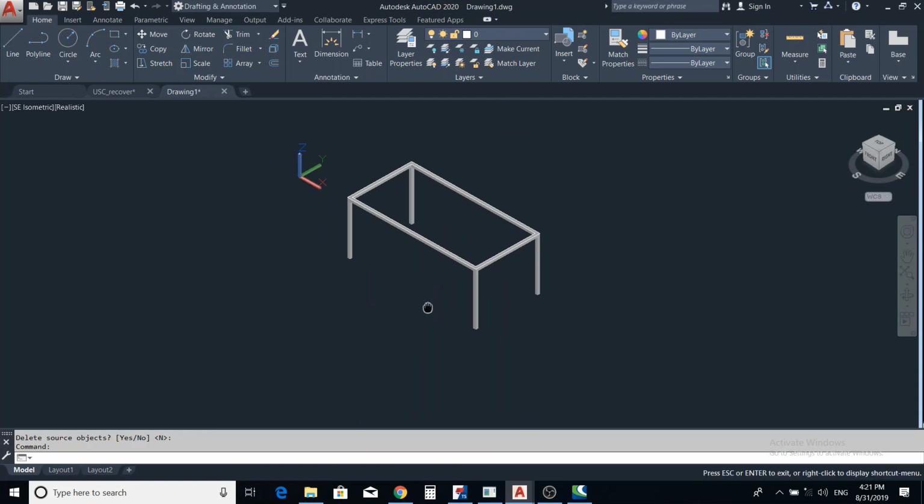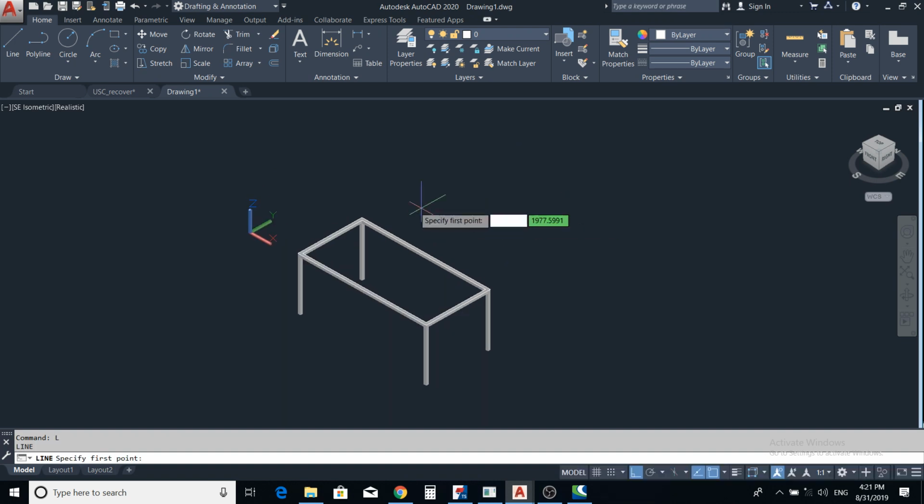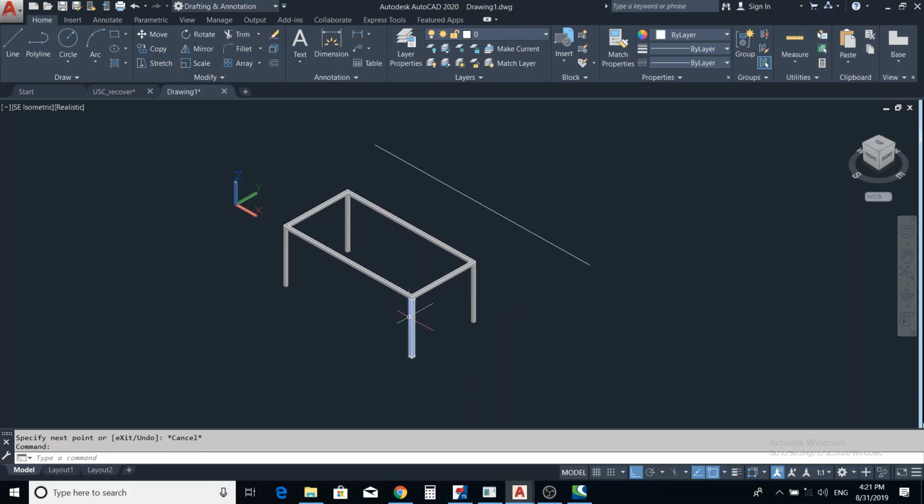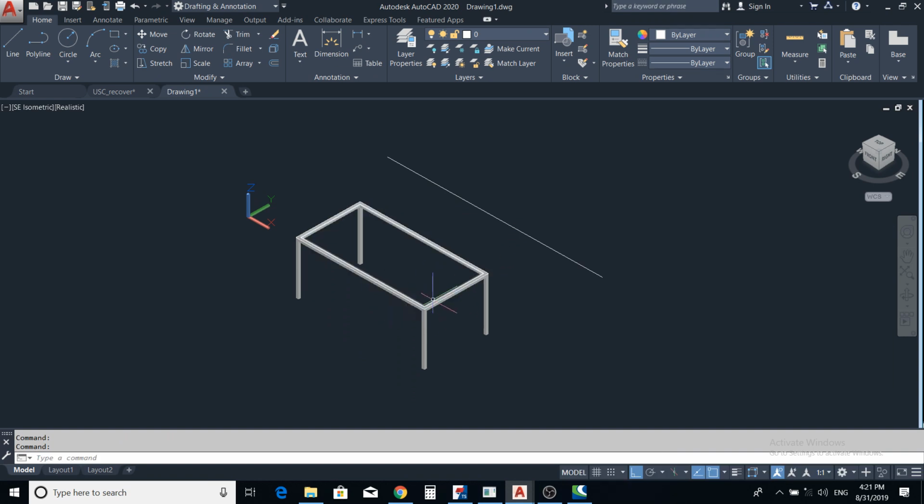You get the point. So let's say, for instance, I have a line here, and then I want to mirror this table about this line. Is that okay? So when you watch it carefully, for me to decide what is the plane of mirror for moving this table, I'm basically traveling along the y-axis. So after selecting the object, I'll be traveling along the y-axis. So the plane that is perpendicular to the y-axis is the x and then z plane.